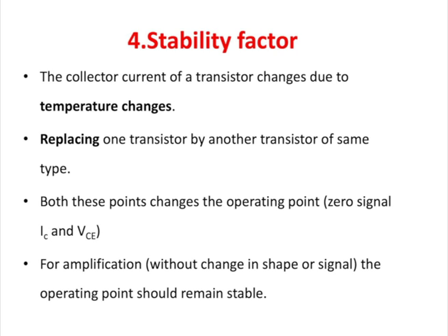Here, what is stability factor? Suppose I am replacing one transistor with another transistor. The configuration, meaning the parameters, of one transistor differ from those of another transistor. So if I replace one transistor with another, the readings will obviously change. Suppose the temperature changes, one day the climate is cold, another day it is very hot summer, at that time the readings will also change. So I want the transistor parameters to stay fixed if the temperature changes or if I replace the transistor with another transistor. That is called stability factor.